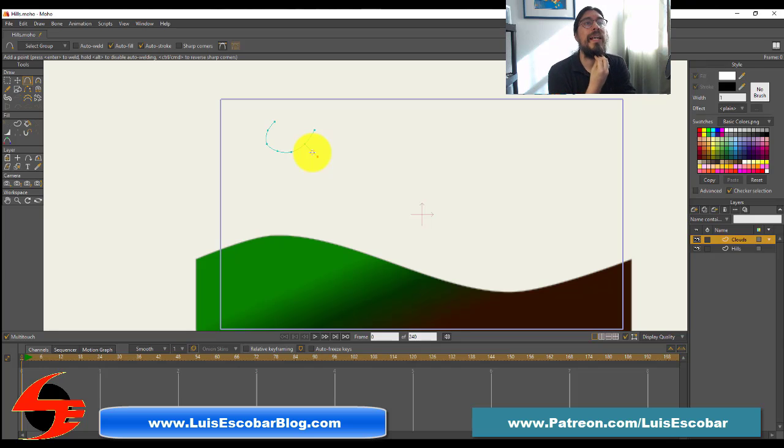So let me see. The key point to remember is to extend the curve. You need to click on one of the endpoints and then drag the mouse to where you want the endpoint to be. Remember, if you make a mistake at any time, just use the undo menu. Okay, now we're going to add a second puff to the cloud. Move the cursor to the point. Yeah, so what I discovered here is that when you put the thing down, you have to go back into it and drag it out. That's how it works.